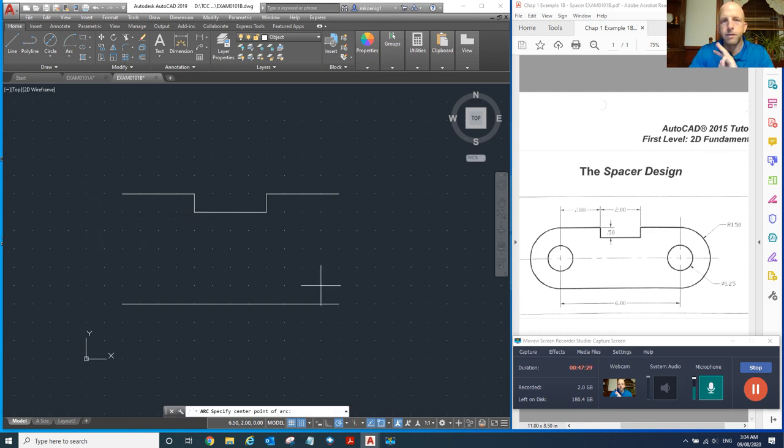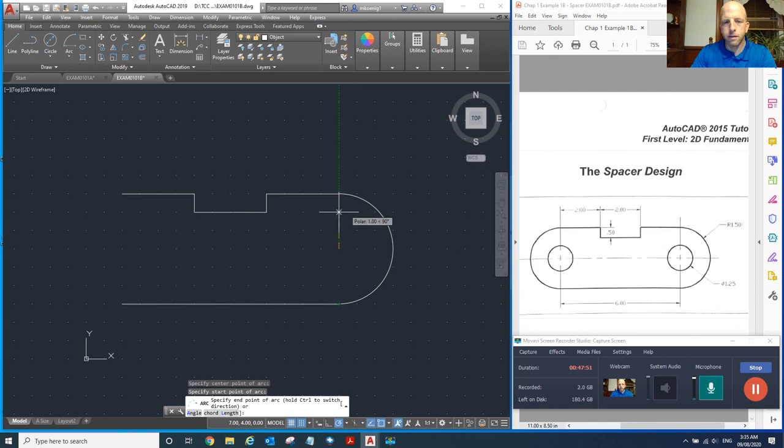So there are the 3, you need 3 points to draw an arc, and that's the order we're going to choose this in. So since I have the snap on, I have a point right in the middle, so I can start my center there. And arcs are drawn in the counterclockwise direction, so we're going to want to start at the bottom for the second point, and then click the top point.